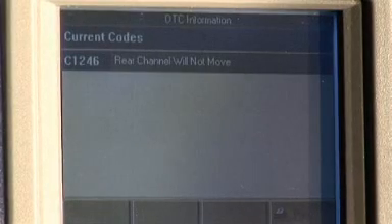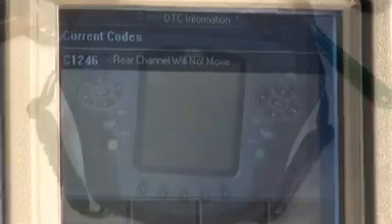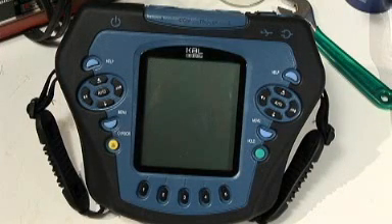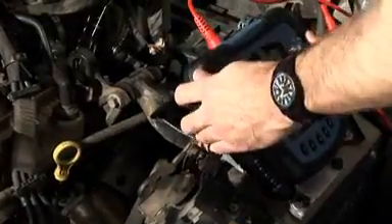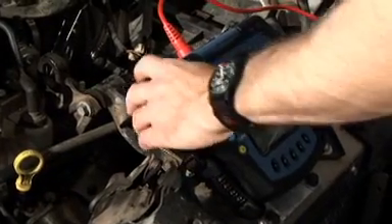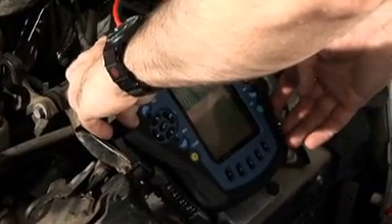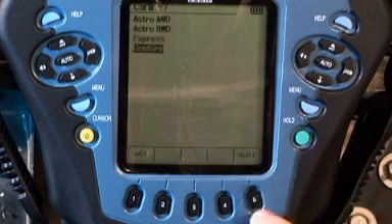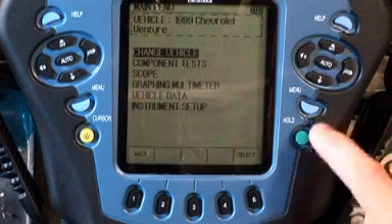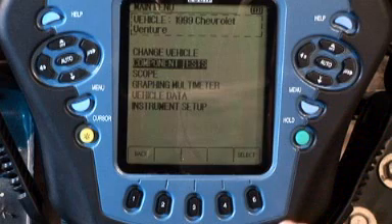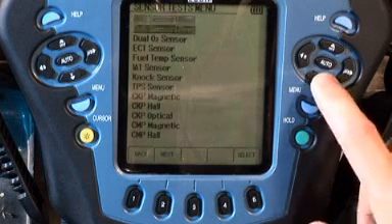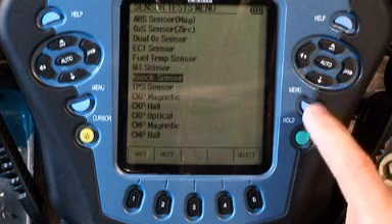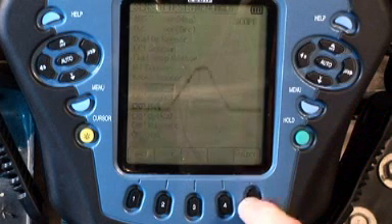The Nemesis displays the TPS fault code. At this point, the technician knows to use a 2-channel scope by OTC. The 2-channel scope provides impressive performance at an economical price. Vehicle make, model, and year are entered just as before. The 2-channel scope allows the tech to analyze the TPS sensor signal by selecting the preset test from the component list. In addition to analyzing the signal, this scope also provides wiring diagram and reference waveform information for many domestic and Asian vehicles.